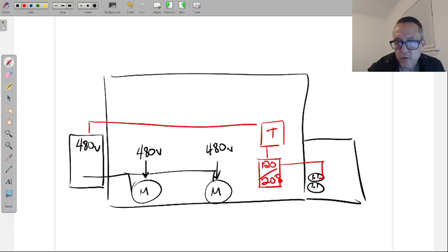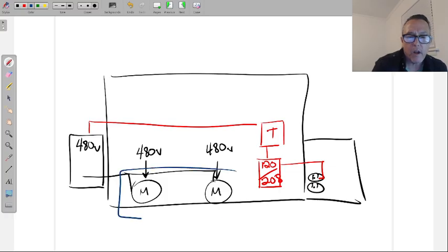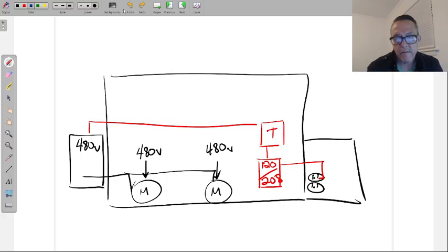So inside this building, usually in an electrical room somewhere, there's a transformer that's taking the 480 volt power and stepping it down to a lower voltage, usually 120 and 208. Now this allows you to wire up your outlets. So for my construction electricians, these are the transformers you're going to see a lot. I hooked up a lot of these.